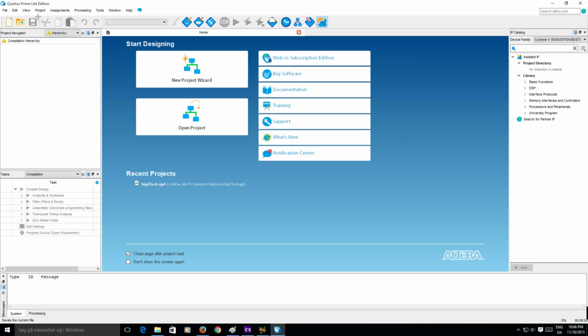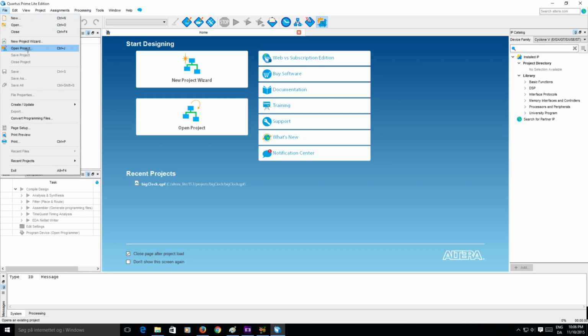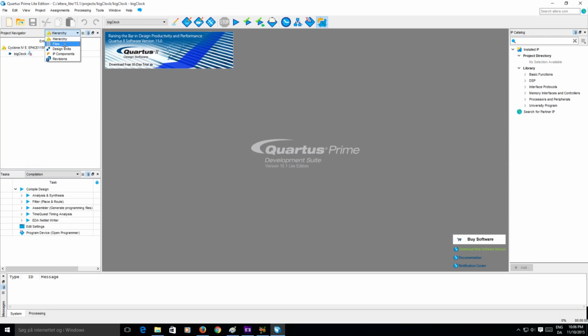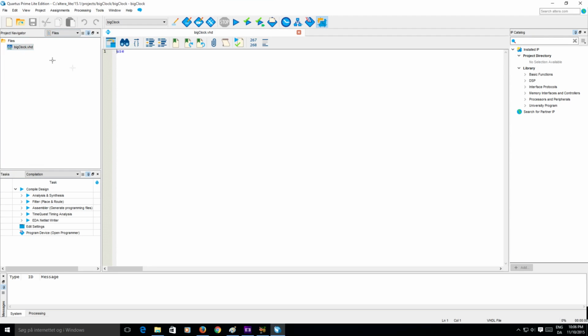So we go into the Quartus Prime software, and we already made a project in the last video, so we can open that. Projects, big clock, and I found my files tab. It's just up here now. So in the last video I just wrote some text here so we could save the file, and actually we need something first. We need to tell it that we use a library called IEEE, and that's with the library keyword. And then you use semicolon to terminate a line like you do in C or C#, C++.